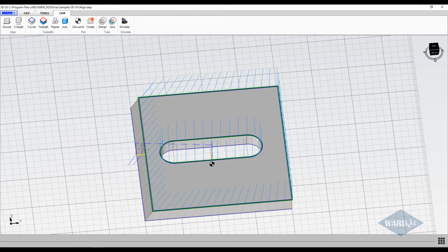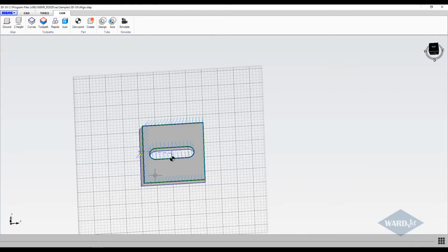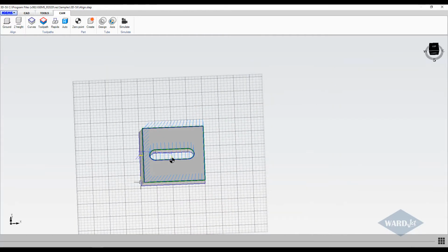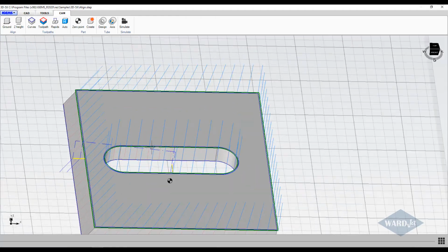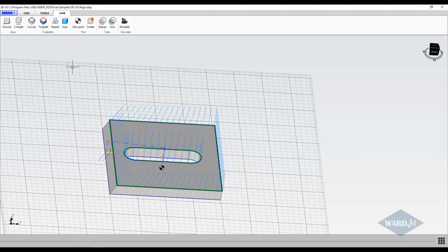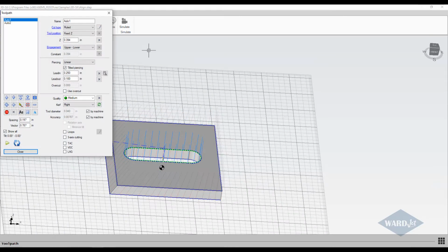Maybe you want your lead in, lead out at a different position. You might not want to lead in on going into the bevel cut. You might want to do this a little bit differently, as far as maybe do the outside as 2 separate cuts where you cut the bevel cut first and then you stop and re-pierce and vertically cut this. Sometimes you'll get a little bit better cut result if you do that. So if you want to change things like that, you can go to this toolpath area here, and now here it shows the 2 different cuts that are in this part.